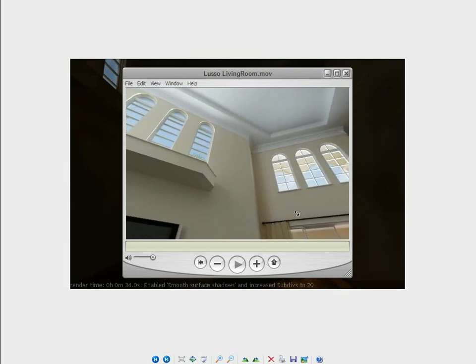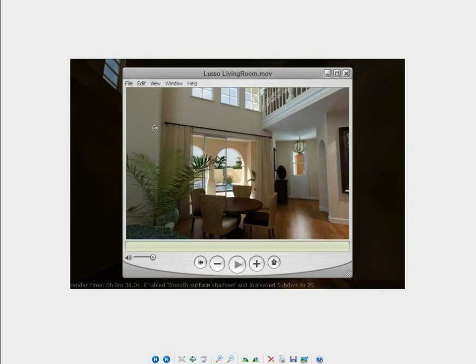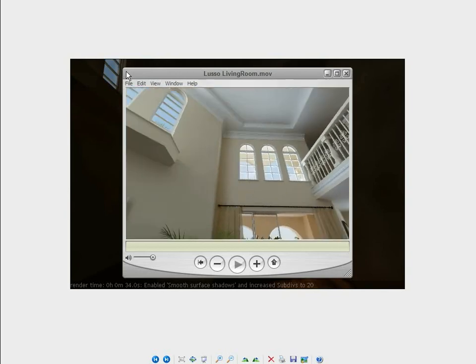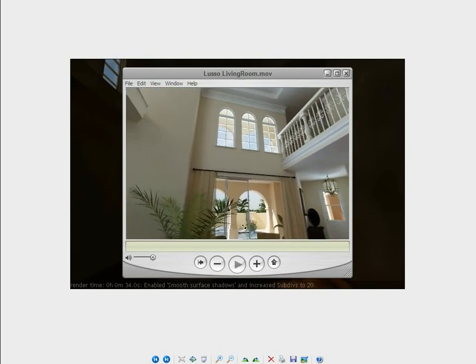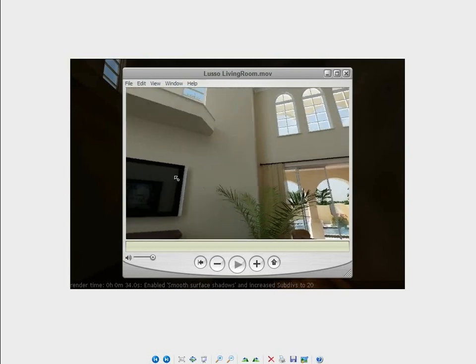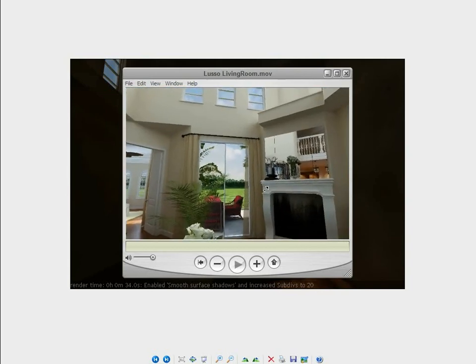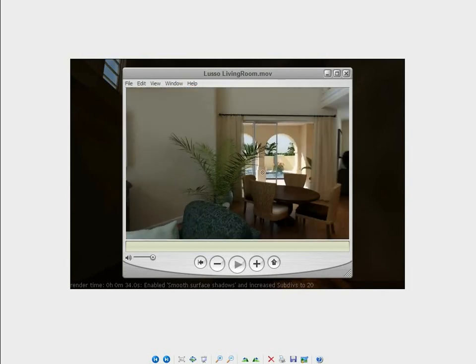In other words, if I look at this panorama and I know that the sun is off to my left, coming in the left side of the house, then it would stand to reason that the intensity of the fill lights on the left-hand side of the view would be greater than intensity values placed in openings on other sides of the building, not facing the sun directly, like the windows or doors behind me, directly in front of me, these sliders in front of me.